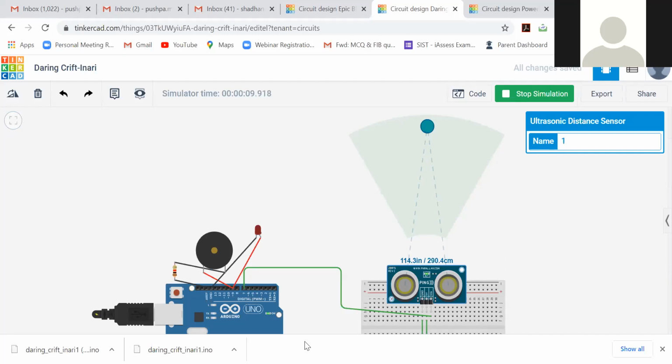It will have a receiver and emitter. It mainly measures the distance. I told you, in reverse car parking, we are using ultrasonic. It will detect the object which is very close. So you just see, this is my range of the ultrasonic sensor.